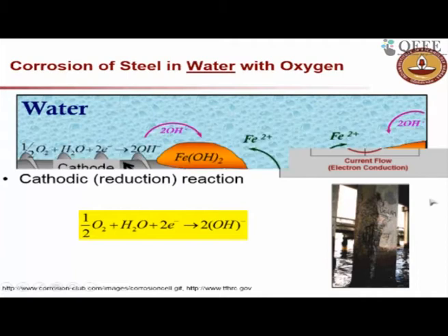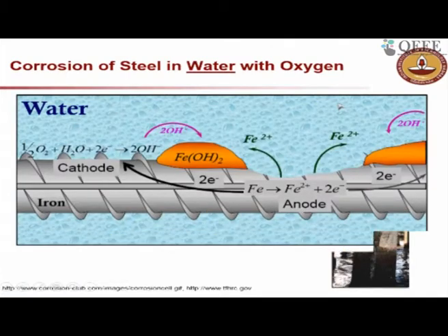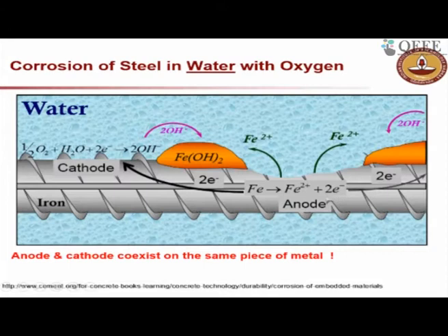Now, with the same equations, I am putting this in a slightly different perspective. You can see the anodic side, where the steel is embedded in the water and metal is lost. The Fe2+ ion dissolves into the water, coming out of the steel rebar, and the 2 electrons released move towards the cathodic side, either to the right or to the left.